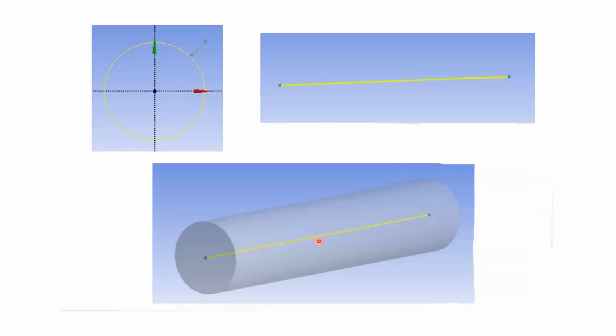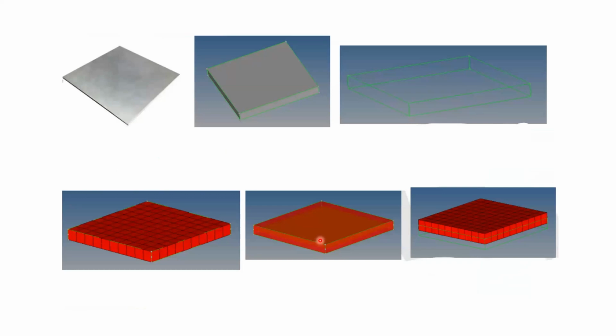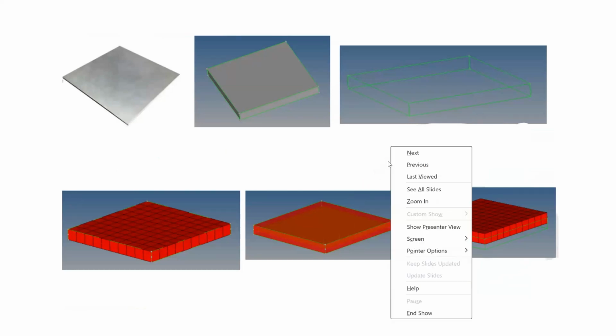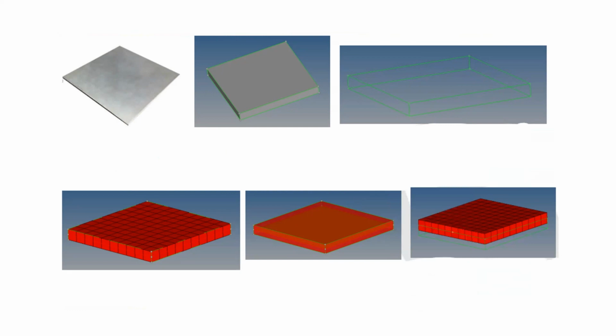I'll show you another clear image. Just see here, you have the mid surface, right? Can you see here? This is the mid surface. Now, when you provide the thickness, the positive half will have half of the thickness and the negative half will have the other half of the thickness. If you are not extracting the mid surface, then your meshing might go out of the actual thickness.